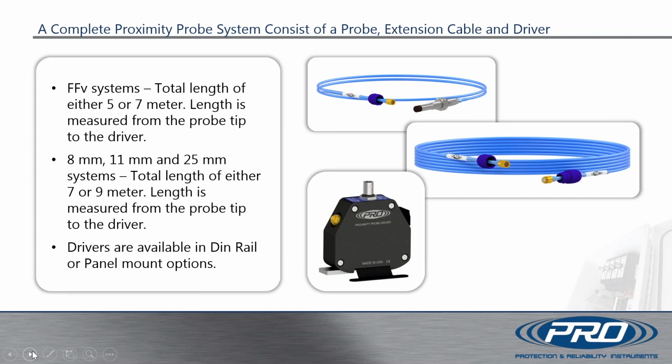The 8 millimeter, 11 millimeter, and 25 millimeter probe systems that CTC offers come with a standard length of 7 meters or 9 meters. Again, this length is measured from the probe tip to the driver. Drivers are available in DIN rail or panel mount options.